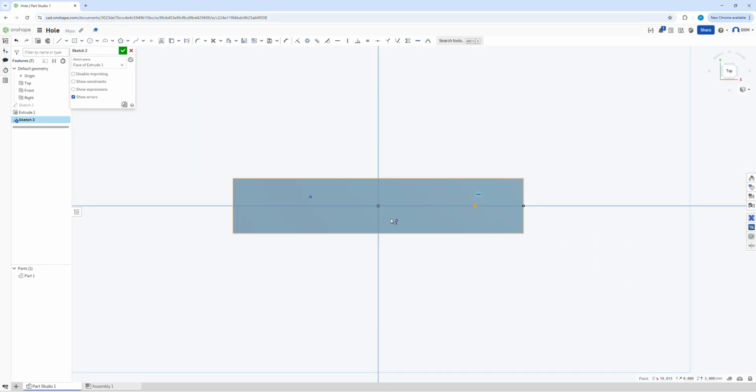I can then get these ones all lined up here, horizontal as well. I can take this one and I can make it coincident, so they're fitted together. And then for these ones over here, I'm probably just wanting to add a dimension from maybe the midpoint. So let's say this one is going to be 15 millimeters, and this is also going to be 15, so it is nice and symmetrical. There's a few different ways you could have done this, but that will do the job for now.